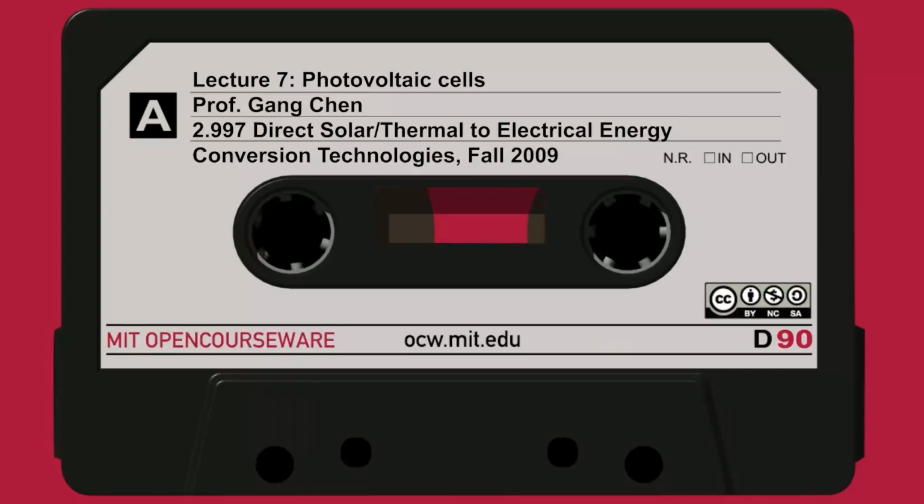Okay? And there's the electrochemical potential. That's what happens at the junction. It's sort of like the Schottky barrier, but they want to make an ohmic junction at those sides. And if you think about the Peltier effect, right? The Peltier heat is the kinetic energy part, which is about 2 kT per charge on average, minus (EC minus EF), the chemical energy.